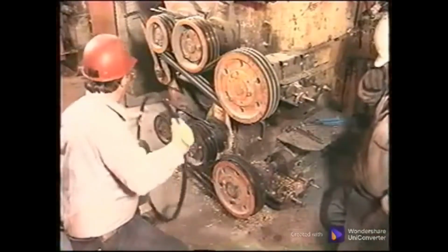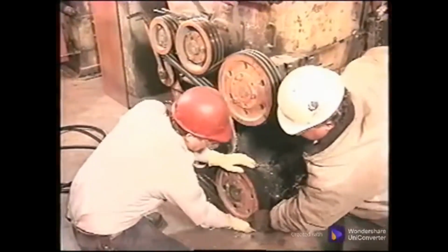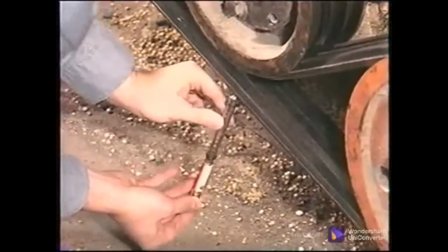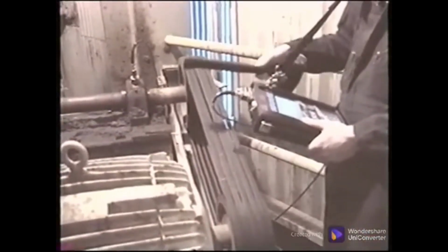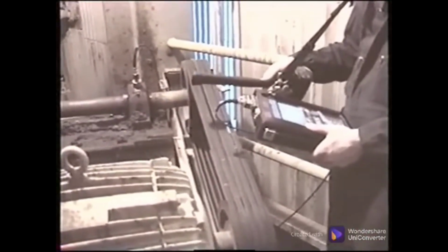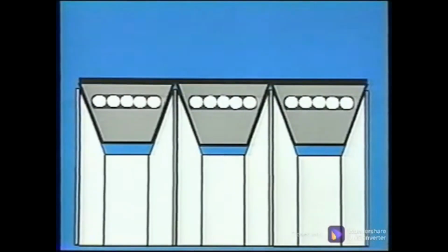Use the belt that fits the sheave and that will carry the design load. When replacing a worn belt in a multiple belt drive, replace all the belts using a matched set. Set the belt tension, making sure that it is tight enough so it does not slip. Determine the belt strand resonance and compare it with system resonance and other forcing functions to ensure it will not be excited by them. Replacing multiple belts with a banded belt will change the resonant frequency and may move it away from problem frequencies. Record this resonance frequency for future analysis.